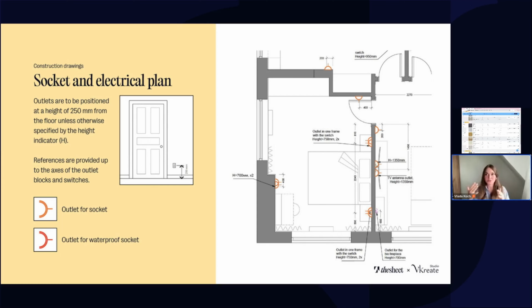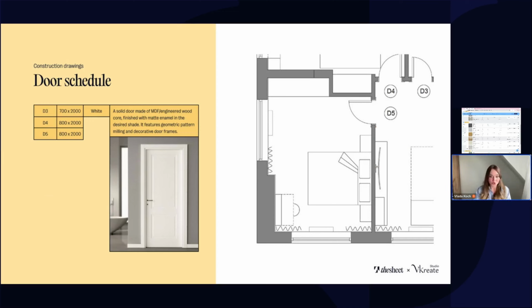They're not much more expensive than the normal sockets. They just have a waterproof system. That's very important for the water areas, for the areas where you can have access to the water. And all the other sockets could be stated in another color. As you can see here, I state the normal sockets in orange, and in red, I state the waterproof sockets.